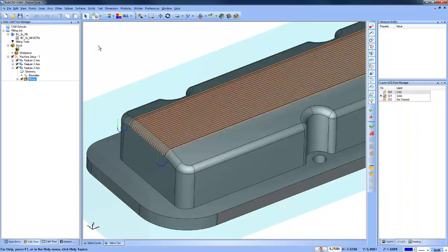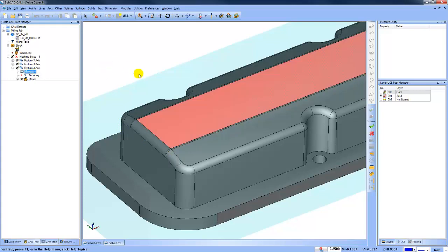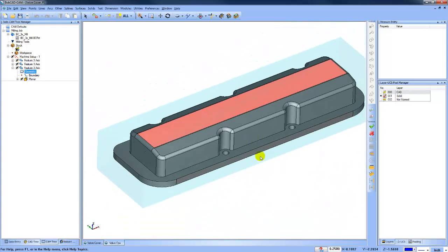So the answer is you can just select one surface. Where you're going to run into issues is the neighboring surfaces. In our 3D toolpaths, we have built-in gouge protection, and it's based upon what you've selected. So if you only select a single surface, that's the only thing the software is going to see. So it can be problematic, especially if you have other surfaces that the tool could run into. So yes, you could just select a single surface, but it could run into problems.